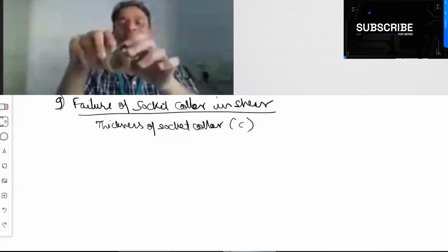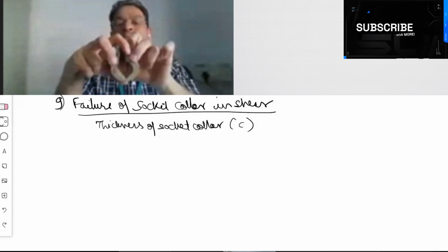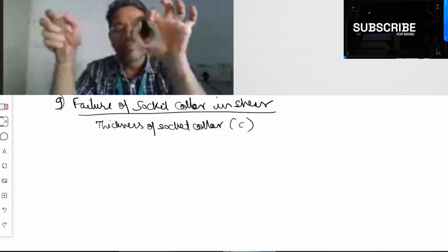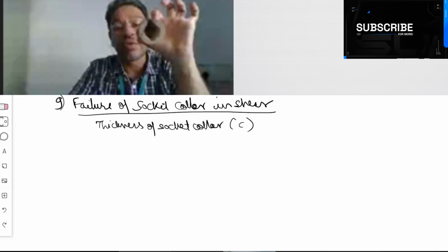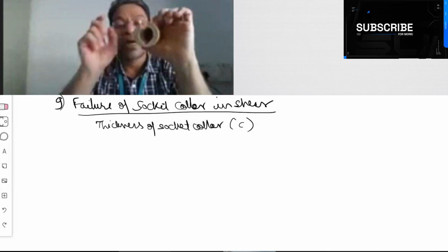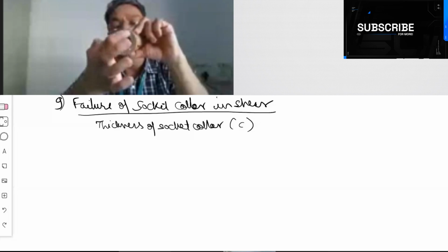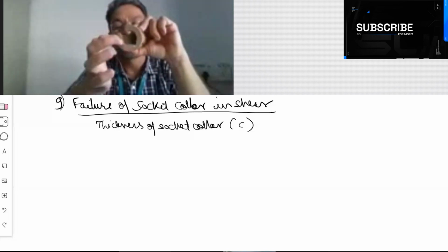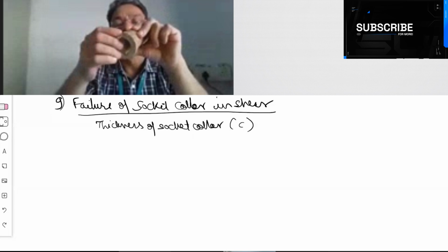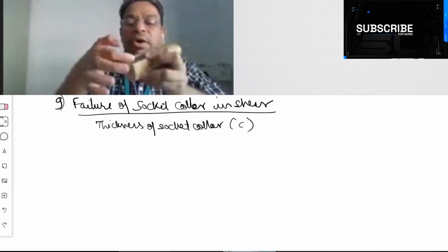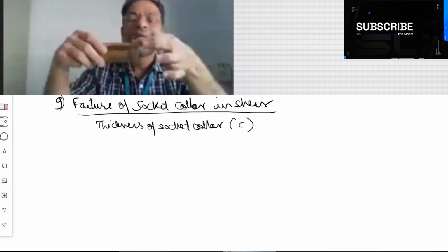Can you see this? इसको तोड़ के बाहर आ जाएगा. ये पूरा राउंड था, अब इसने तोड़ दिया और ये बाहर आ गया कॉटर. तो क्या हुआ है? फेलियर हुआ है. कौन सा फेलियर हुआ है? शेयर फेलियर. कहाँ से टूटा? ये पूरा कंप्लीट राउंड था, ये यहाँ से टूट के आया. This is the area from where failure has happened, and this is the area from where failure has happened.